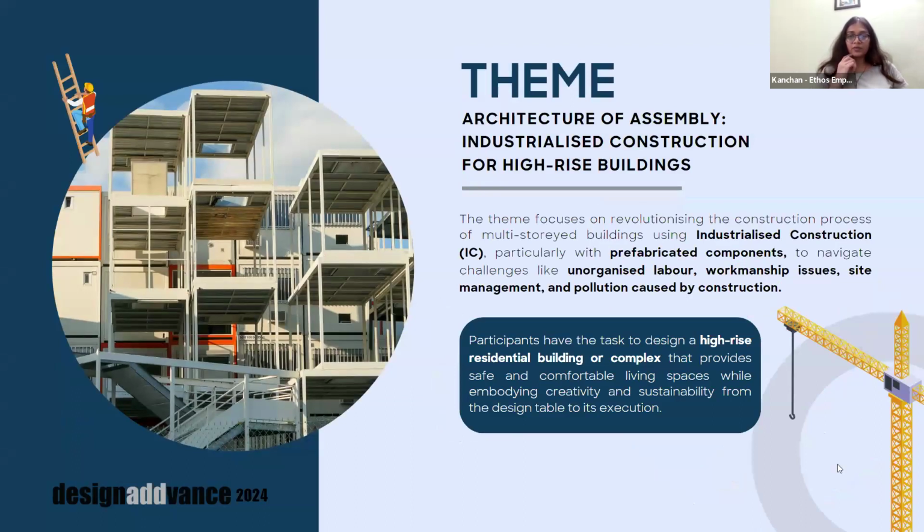Let me just introduce what architecture of assembly means. Prefabricated construction, some of you might already be aware, or some of you might have already heard of it. It is where the components of a building, whether they be something like wall panels or floorboards or ceilings or doors and windows or something as big as an entire bathroom or a kitchenette, can be prefabricated in a factory and then later transported to the site together and assembled in a short time.